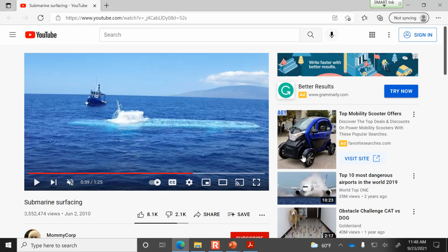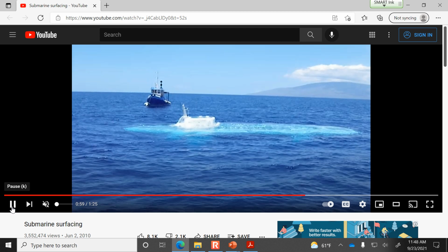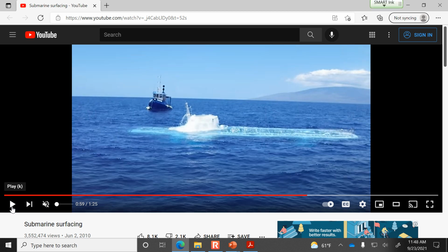The equilibrium is taking into account the weight of the object and the external buoyant forces that are acting on the object. And so if it's still rising, what does that tell you about the balance of forces between weight and buoyancy? There's more buoyant force pushing it up. That's right. There's more buoyant force pushing it up if it's still in the process of rising. So let me just take it back a couple of frames. Still rising, there must be an imbalance of forces.